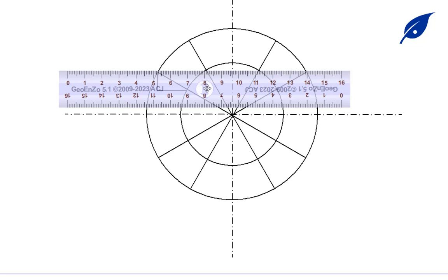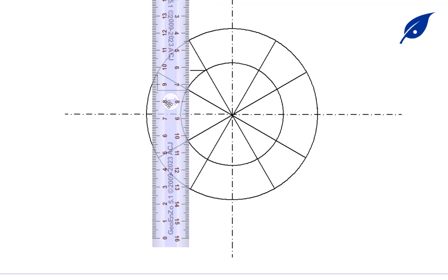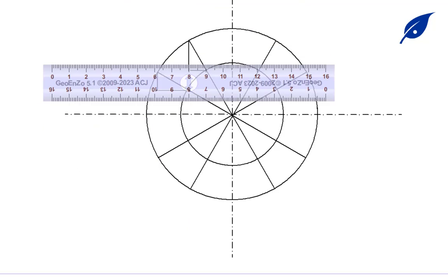So now the point of division of the circle, horizontally from the smaller circle, then vertically from the large circle, you draw a line to come and meet each other, and both lines will be perpendicular, that's 90° to each other.